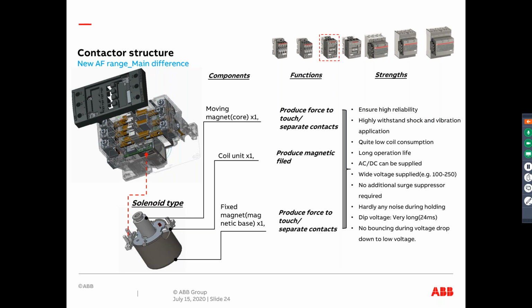It's hum free, and the specialty about it is that this is the only contactor which can be used for semiconductor industries, because it can take a voltage dip of 24 milliseconds, and that is very long. There is no contactor in the market which can do that at the moment. So we are certified for it as well. And basically there is no voltage drop, no bouncing of contacts.